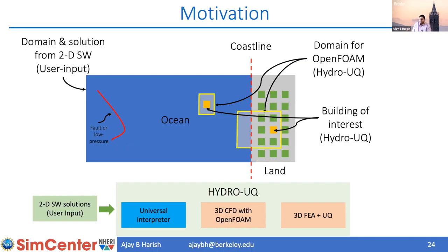And what HydroUQ does is it has a universal interpreter that reads these solutions and sets up a CFD simulation with OpenFOAM. When I say setup, it helps you to set up the boundary conditions, and it also helps you to set up the geometry.